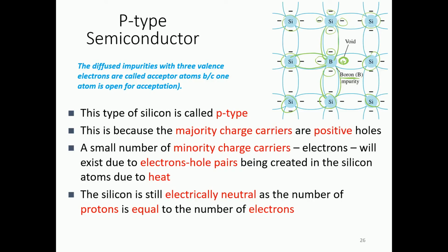So now this hole is open. The electron of silicon, which is free, can easily come and join this hole. So again, this can become a conduction element. Again, if this electron moves from here and fills this hole, a hole will be created over here. Similarly, another electron from another boron element, let's say if there is a boron over here, this electron will come and fill this hole, and this process keeps on continuing in this lattice structure. So we have created a p-type semiconductor material. This is known as p-type. It has majority carriers which are positive, or we call them holes. Minority carriers are electrons, and thus we create a p-type material by an external influence, or what we call doping.